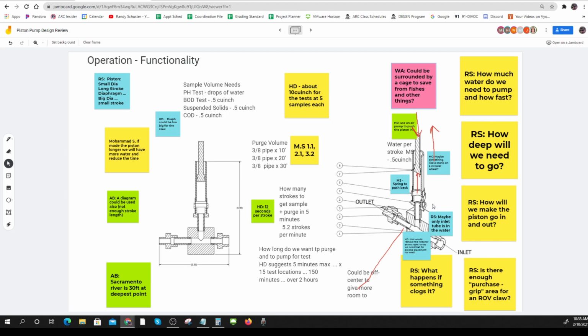You basically blow the gunk off with back pressure. So if you've got air here and you got a little valve right here, you could use that air to back blow everything off of the cage. Poof. It blows everything off. Okay. And so that's something that you might think about doing. But yes, it needs to be a cage. Replace the filter or reverse the flow. Yep. So there we go. So Alex says you either replace the filter or reverse the flow.